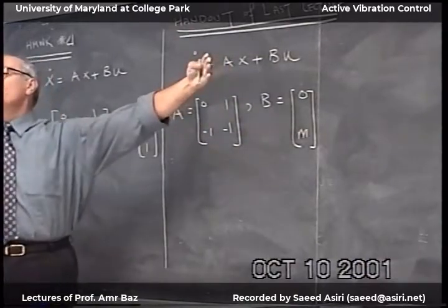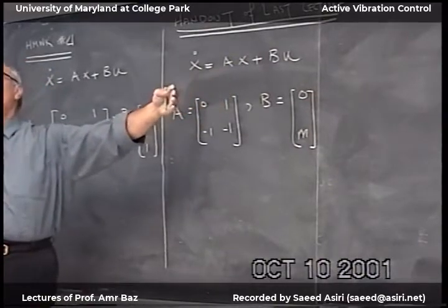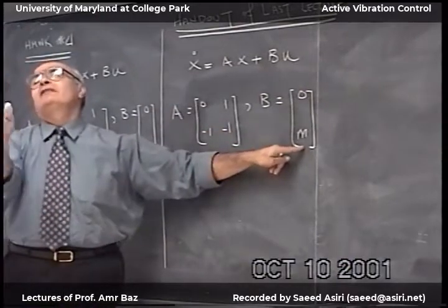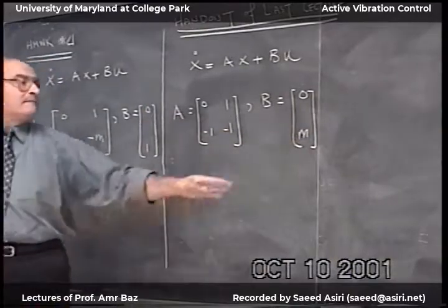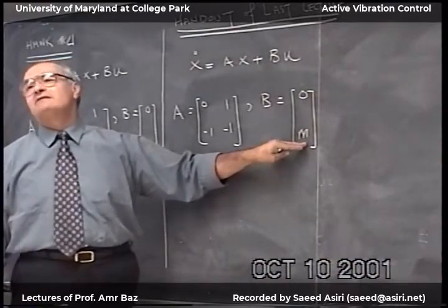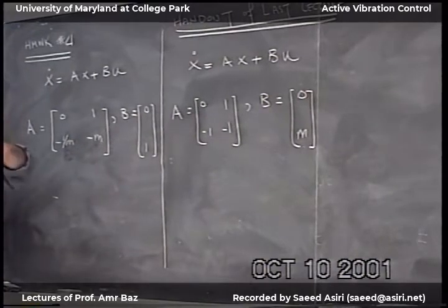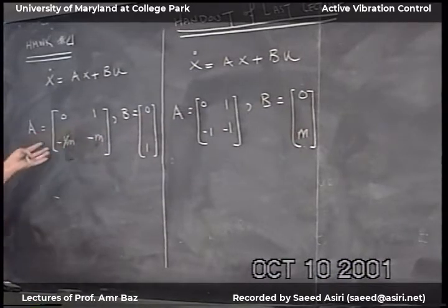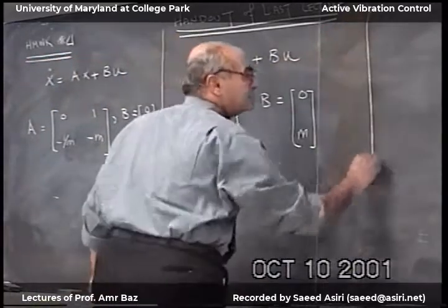In a large system, you say I'm putting the actuator at 1 meter from this end. That's what you think, okay? But actually, maybe you put it at 1.05 meter. So you have deviation from where the physical modeling location was, and you have some error or uncertainty of where you locate the actuator. So these two can create a loss of robustness of the controller. So the two look very similar.